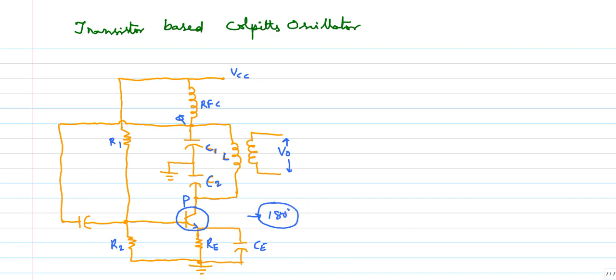And resistors R1, R2 and RE are used to set the desired operating point. So these three resistors establish the operating point, and operating point can be defined based on these three, R1, R2 and RE. So these three should be properly designed to get the proper operating point.